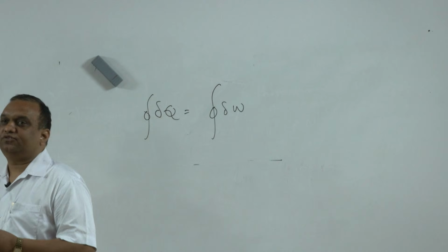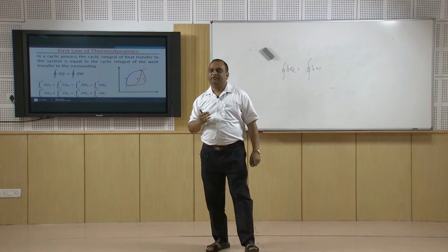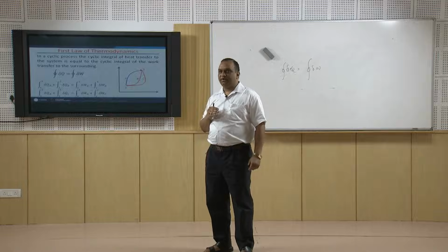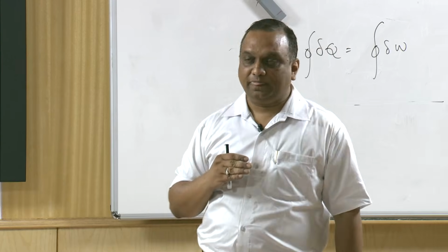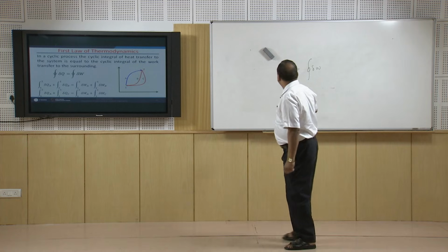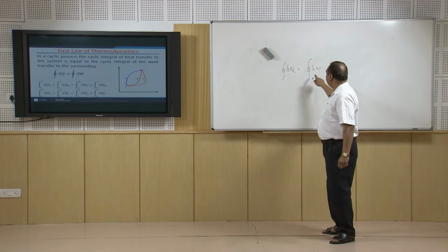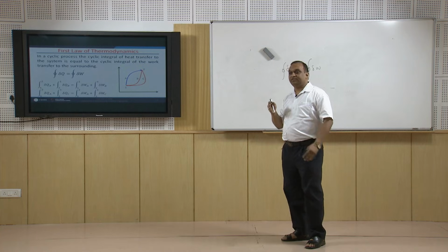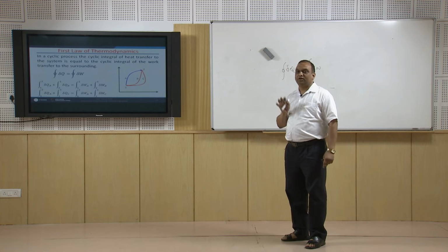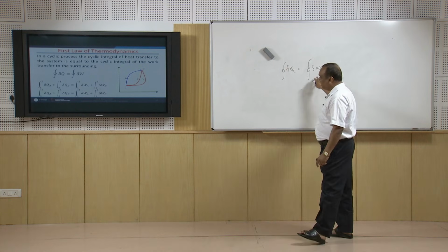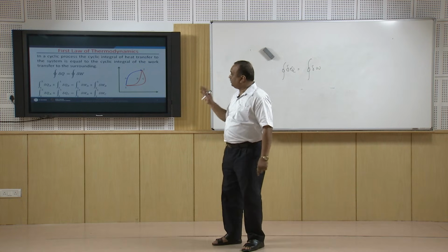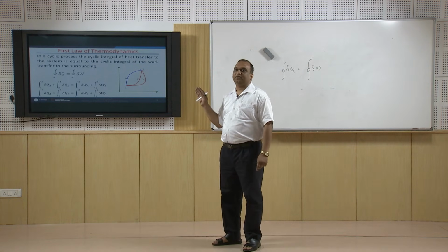Now, in thermodynamics, when heat is given to the system, it is taken as a positive heat transfer. When heat is extracted from the system, it is taken as a negative heat transfer. Similarly, when work is done by the system, it is considered positive, and when work is consumed by the system or done on the system, the sign is negative.